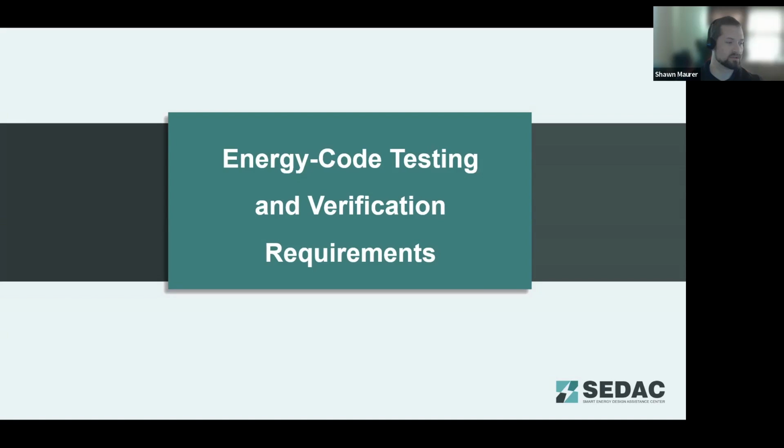And for the last one, commercial requires only testing of that high pressure duct section. So low pressure ducts that are in that lower pressure class of 1 or 2 inches do not require testing. So a little bit of a tricky question there, but it looks like most people got it correct, that only that high pressure section of commercial ducts is the correct answer there.